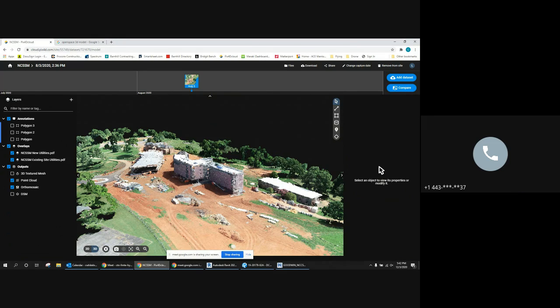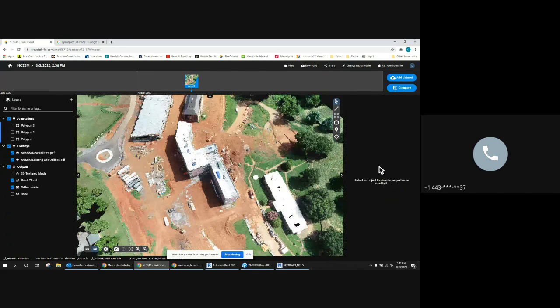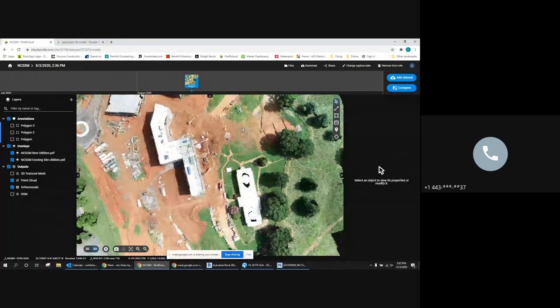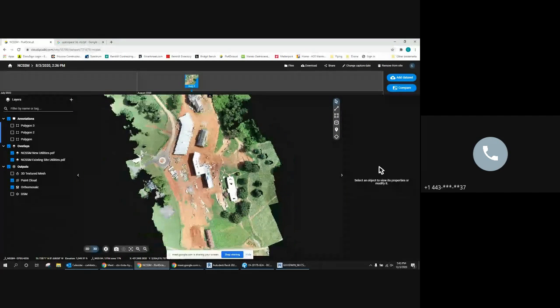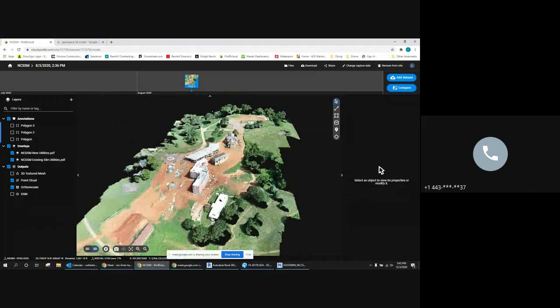Yes. One thing to note, though, the way that we do it with drones is very similar to a total station, but a little bit different. So we have benchmarks, which are just physical points on the ground that a surveyor has laid out. And then from that, the drone can geolocate those benchmark points to determine the geography of where this position is located on Earth. And then we can put it into a program to do that analysis.